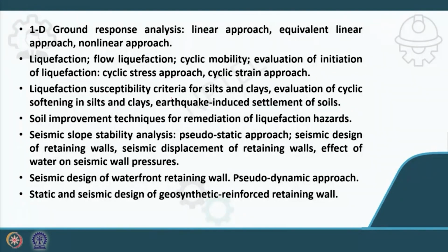And then I will discuss the 1D ground motion response analysis, okay, because sometimes the parameters that we will get are mostly for the bedrock. So then we require to know what the parameters are at the ground surface. So from the bedrock to the ground surface, from a known bedrock motion to a ground surface motion, how we can predict that. So that also will be discussed, and vice versa also.